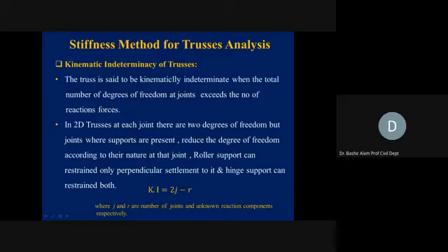So, restraint of the displacement is coming from where? It is coming from the capability of the reaction. If we take the example of the hinge support, it can resist in the vertical direction, it can resist in the horizontal direction also. So horizontal and vertical displacements are going to be equal to 0.